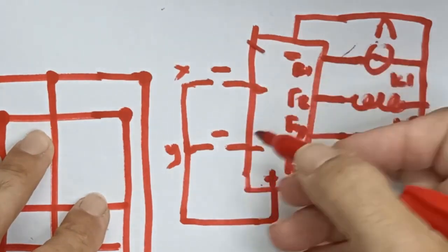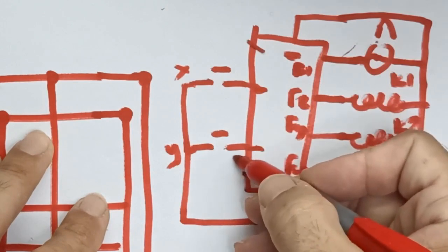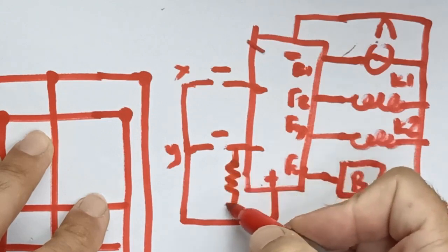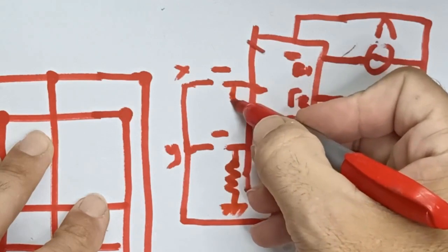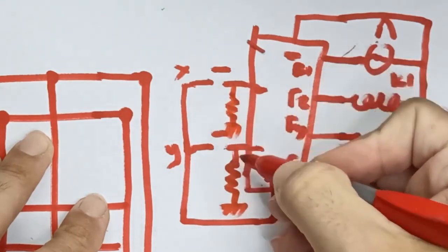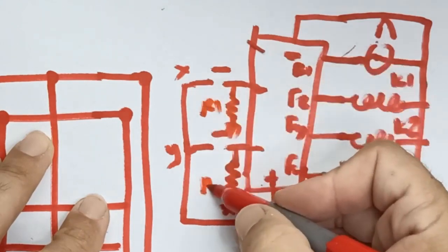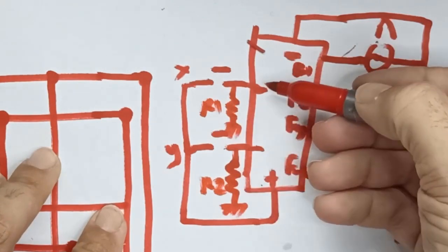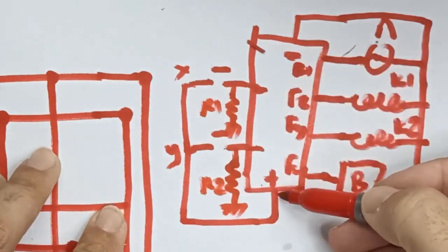And they get confused. They don't know if it's 0 or if it's 1. So we will use resistors here at the inputs, around 2 kilohms, on both, and we will adjust them to have a clear 0. Here are the inputs. And when we close the button, they will clearly receive the 5 volts. Just as we multiply the transistors, we will multiply the inputs here too.